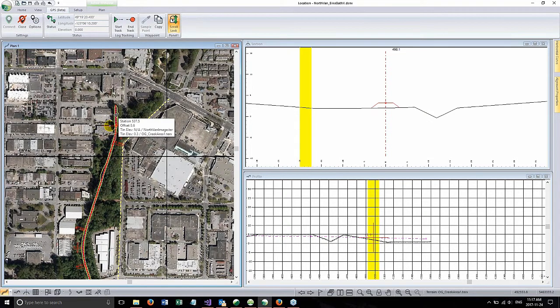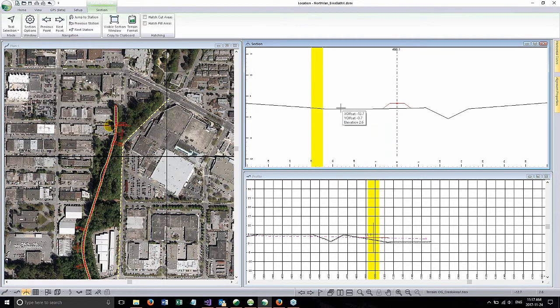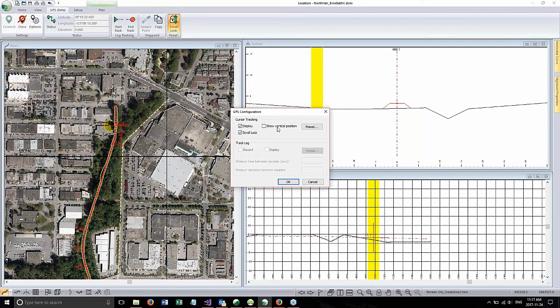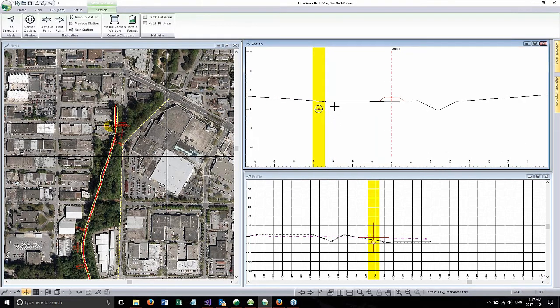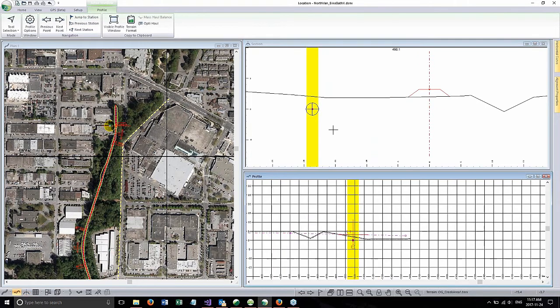Accuracy, horizontal accuracy, is usually pretty good. A mapping grade, maybe 1 to 3 meters for reasonable mapping grade. Vertically bad, and I would caution you to be really wary of what you get back vertically. I've seen huge differences. And the way to turn on the vertical position of the GPS is to go in here to Options and Show Vertical Positions. By default, it's off.